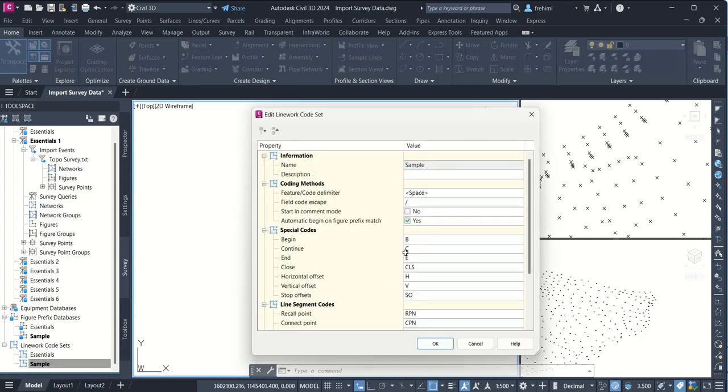If you edit this, you will have this. And normally, this interface informs about what? Informs if you have, for example, to link the center line of a road. You would like, when you import your files, the points joined with a line, the center line of a road joined with a line. You should specify what is the code for center line. For example, CLRD is for center line, and you should add the code B. For example, in this default, beginning of a line is B, to continue C, to end E.